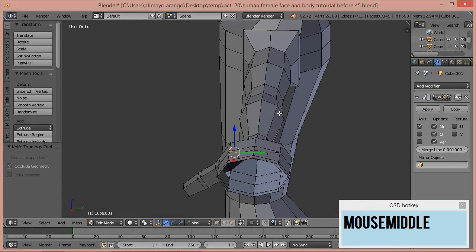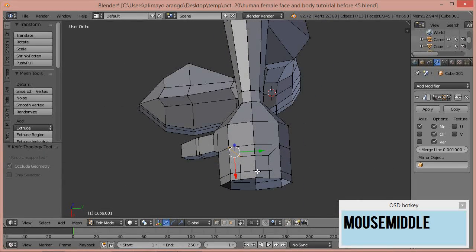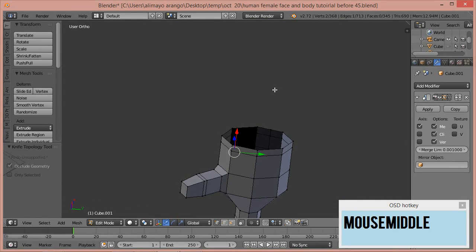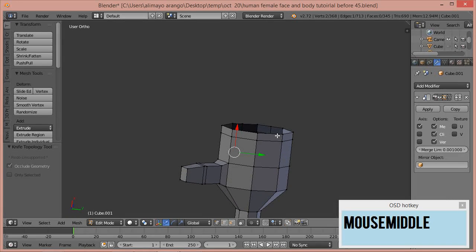So the top part of this hand, you see these four faces, so you're cutting through four faces for the top part. For the bottom part, we're going to cut through 6 faces. So what I'm going to do is hit A to deselect. I'll hit A to select everything. A to deselect. I just do that to make sure I'm totally deselected from everything.